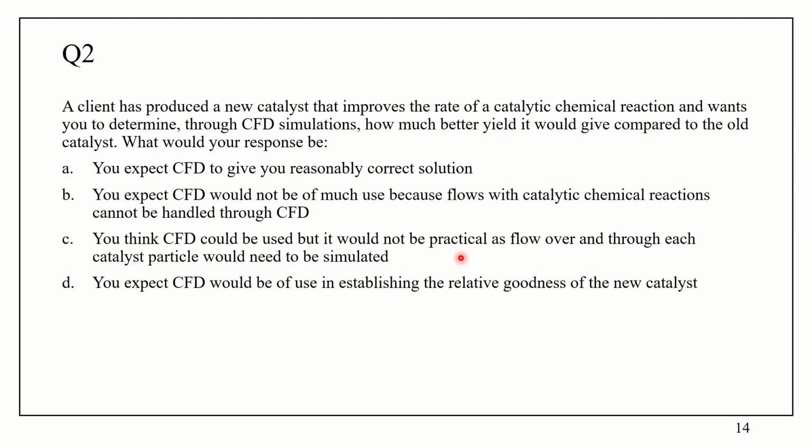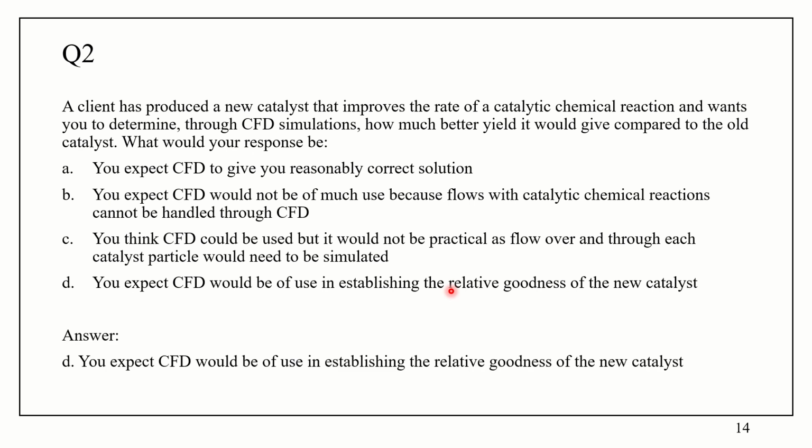For example, in a fluidized bed or in a fixed bed, we just determine the flow over and through each catalyst particle or each solid particle we would study there. Similarly here it would be practical to study the catalytic particle flow. So option C is false. Option D is right. We expect CFD would be of use in establishing the relative goodness of the new catalyst. Therefore option D is the right answer.